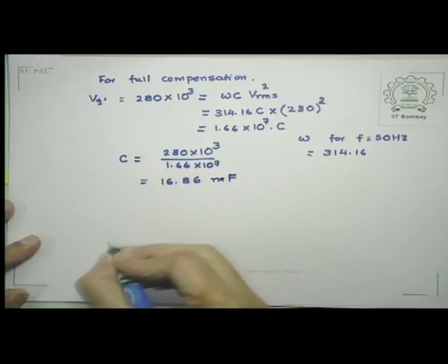So what we have done in this lecture is to have a close look at the LCR circuit, in particular the power factor, which decides how much loss is going to be there because of reactive elements in the circuit. And this is very important because, as I pointed out right in the beginning, if you look at power transmission, the losses, which are popularly known as copper losses in electrical engineering, are given by I squared times the resistance of the cables. So if this I is more, then of course the losses will be more. And a low power factor implies that the current drawn by the load is more.